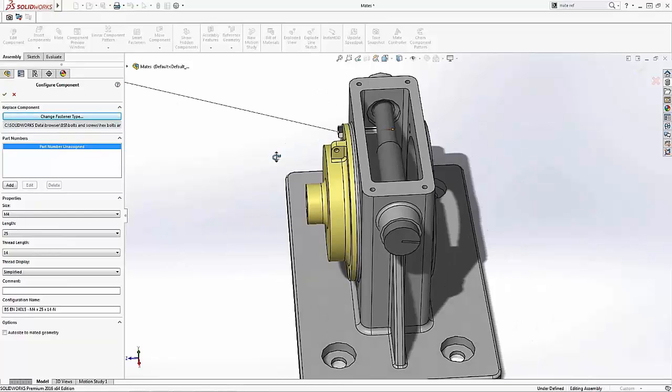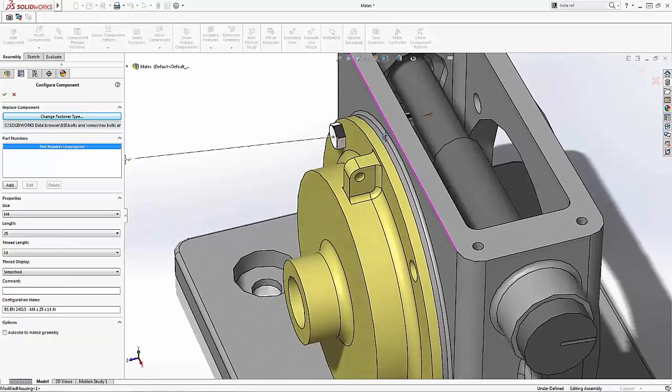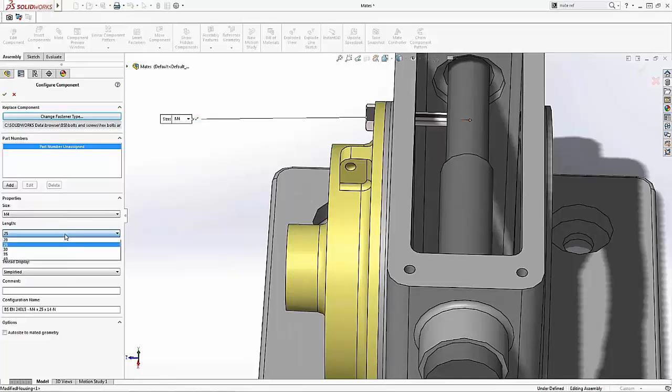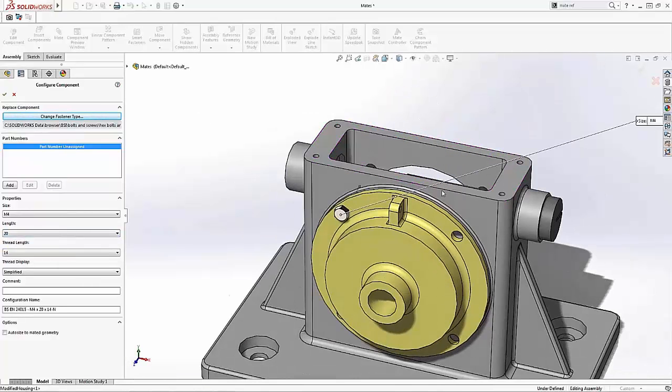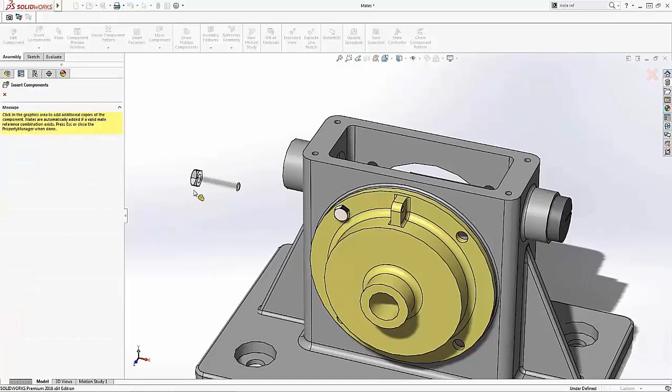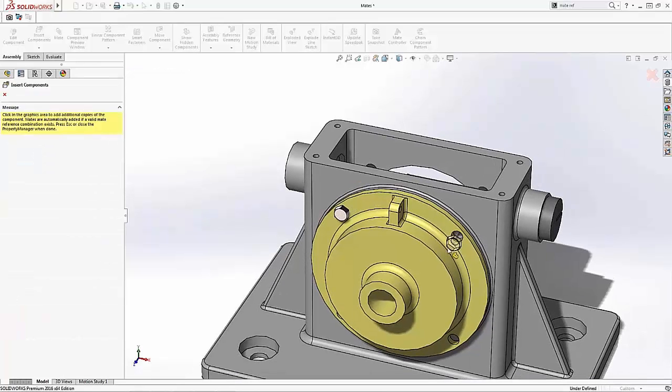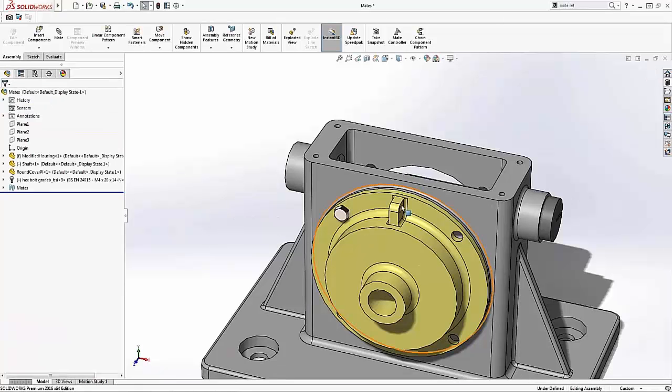Now in my case here, I'm going to go ahead and add a couple of bolts to this. However, this isn't the main tip that I want to give you guys. That will come in just a moment here. First, we'll go ahead and size this bolt. We're going to go for an M4 size bolt, get that into place. And now guys, what I could do, Toolbox does give me the option, as you can see with my mouse cursor there, to place additional bolts.